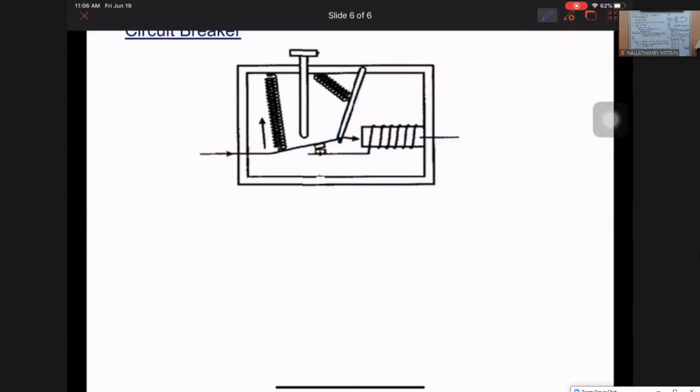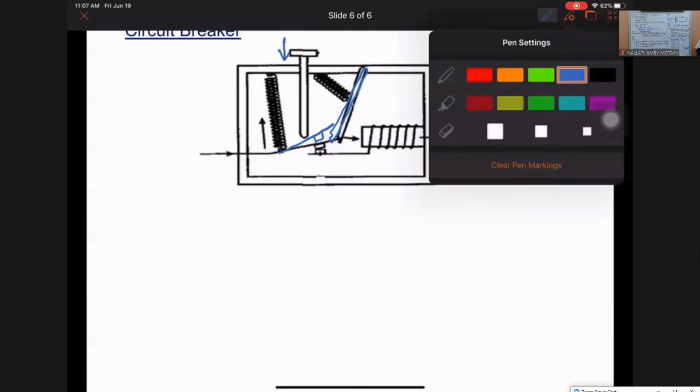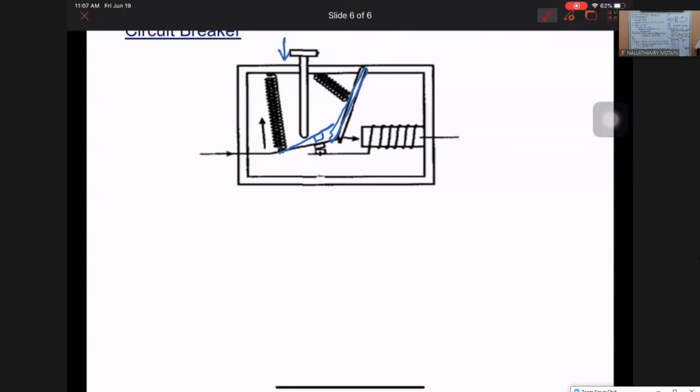Then how are you going to connect again? So let's say the wire over here is already moved until here, right? Contact is here, and this armature is here. So what you need to do is use a reset button. Push using the reset button. Once you push, what happens? This contact will be pushed down. When pushed down, the contact will be closed. Closed, then current will flow again. Then the electrical appliance starts to function.